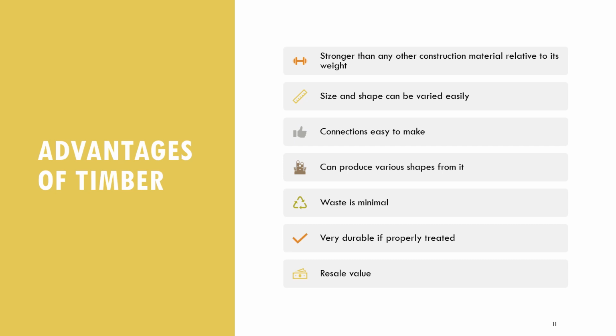Waste is minimal, and the reason for that is because, given that it's easy to handle, it's easy to size and shape your timber structures, usually you can minimize waste because of that. It's very durable, but it needs to be properly treated for it to be durable. So when I say durable, I mean resisting termites and the impact of weather. And it also has a very strong resale value compared to other construction materials.